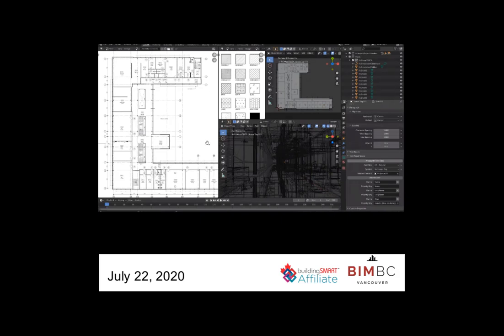But more than that, in this little demonstration, the BIM model is open. It's in IFC form. The software is open source, but the documentation is also open. The documentation is stored in IFC, but it's extracted out in SVG format. So this takes a departure from proprietary formats like DWG or DXF, because SVG is an open standard for displaying vector information.